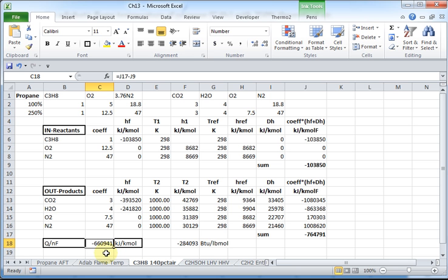All right? So you can see I first have a line for propane, oxygen, nitrogen, carbon dioxide, water, oxygen, nitrogen, all for theoretical air, and then I balance it for 250 and I get the coefficients, 12.5, 47. So then I have to put all my ins, all of my reactants, propane, oxygen, nitrogen, put the enthalpy of formation, some of them are 0, inlet temperature, evaluate that enthalpy.